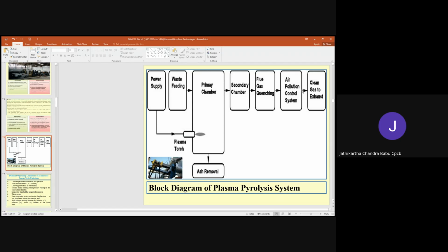Then, after cleaning, the clean gases will be emitted into the atmosphere, whereas the residue generated is collected, treated and disposed. From the cleaning process, ash is also collected and will be disposed of through landfill. In the cleaning of toxic gases, we use wet systems, meaning we use water or an alkaline solution to neutralize the acid gases. Therefore, liquid waste is generated in the process that will go for ETP treatment. After treatment, wastewater is recycled back into the air pollution control system.